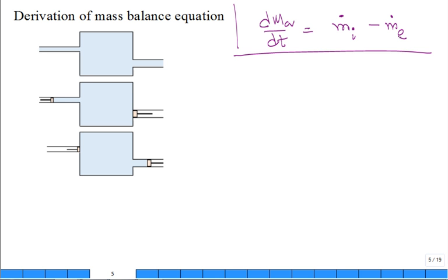to the side. So what I'm going to do is say I'm interested in this being the control volume. It doesn't have to be rectangular, but it's easy to draw it rectangular. So that's our control volume, right? And we want a conservation of mass statement for that control volume. So we'll go back and say, I'm going to consider a system, let me try and draw it with this color, that initially occupies everything in the control volume plus a little bit on the inlet pipe.